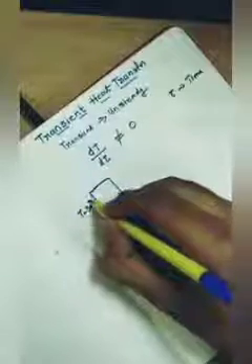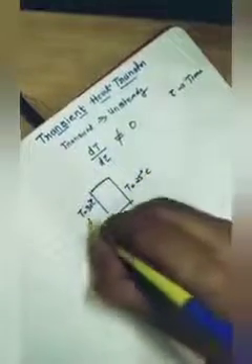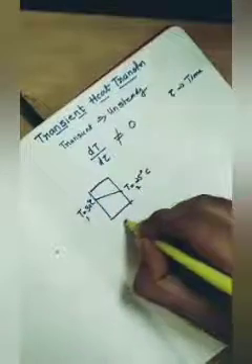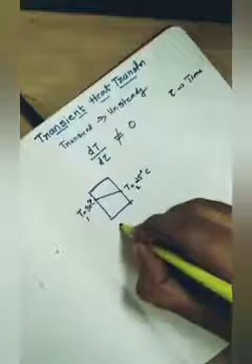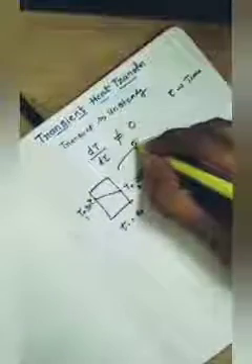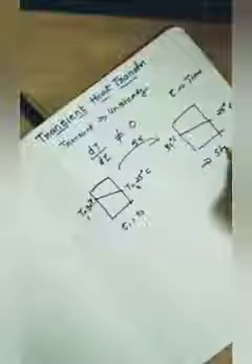So I will make it simpler. Consider a plane wall, and the temperature at this point is, let's say, 30 degrees Celsius, and at this point the temperature is 25 degrees Celsius. Call them T1 and T2. So this is the temperature drop. This is measured at an initial time of 0 seconds, and after 5 seconds, if it shows the same temperatures, 30 degrees Celsius and 25 degrees Celsius, it means it is at steady state.